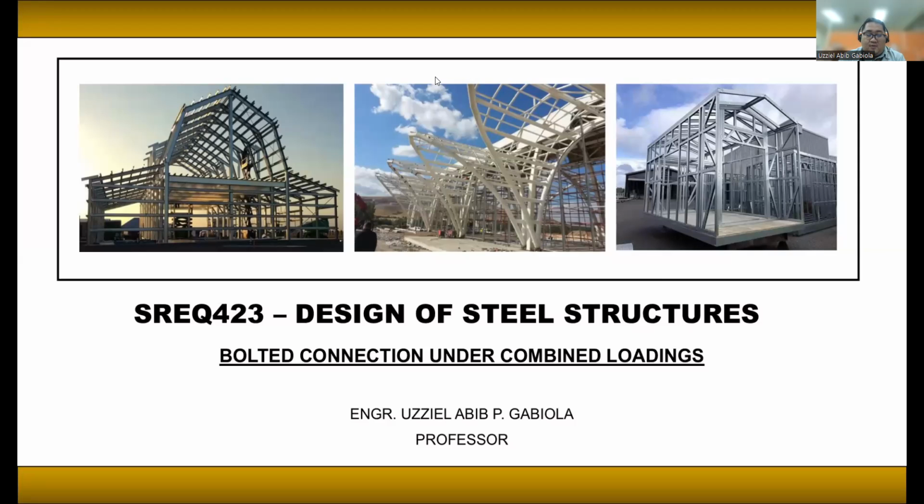And we have witnessed that if we are considering a slip critical connection, most of the time the number of bolts is twice that of a bearing type connection. Because what it considers is to attain the snug tight condition, and to attain that, you need a specific number of bolts to produce enough friction to provide slip capacity for our connection.